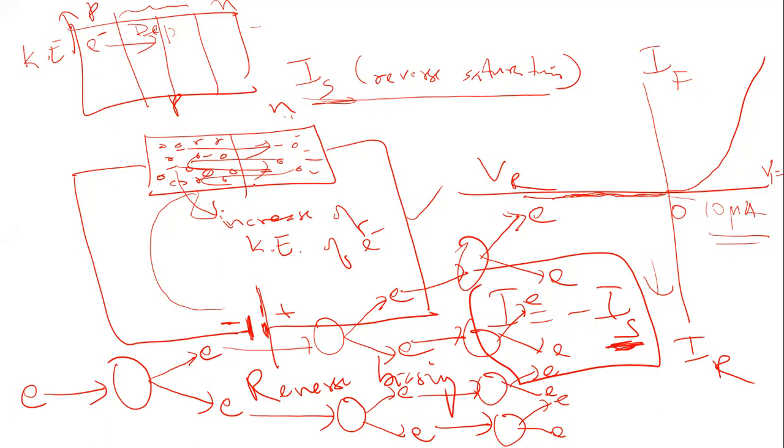When you multiply free electrons like this through collision, the process is called avalanche breakdown. So when avalanche breakdown occurs, large current will result in damage of this diode. It will burn the junction. So under reverse bias, when you multiply these free electrons through this avalanche process, that is inelastic collision, release of another electron, inelastic collision, release of another electron, and the subsequent steps as I describe here using this picture, that will result in very large current, and that very large current will burn the PN junction.